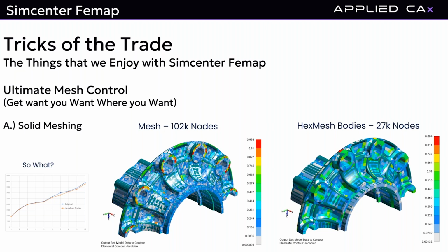The Jacobian is a linear matrix that converts the nodal coordinates from global coordinates to normalized coordinates, -1 to +1, for your isoparametric element. It's a linear matrix operator, but it also gives you a measure of how hard it is to convert that element into a normalized coordinate system.